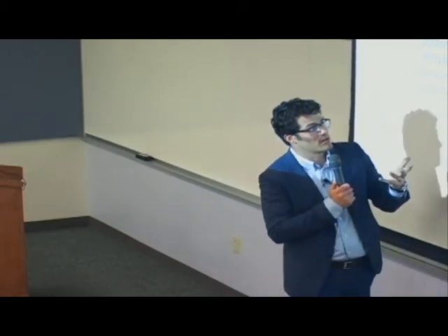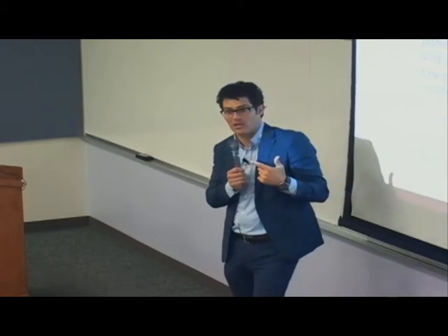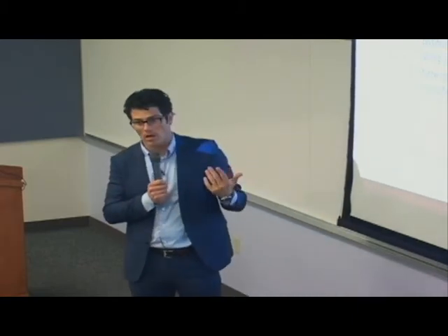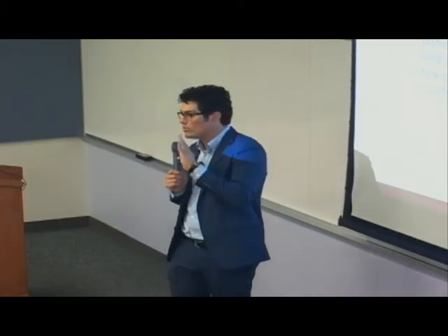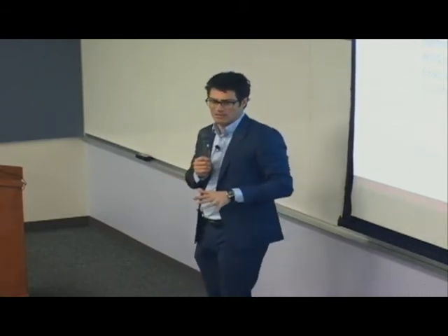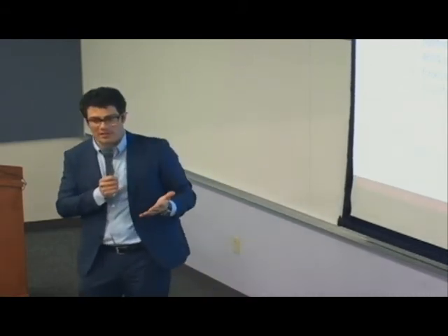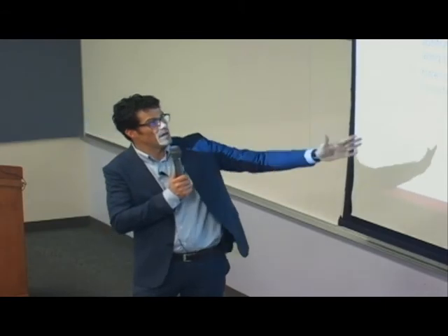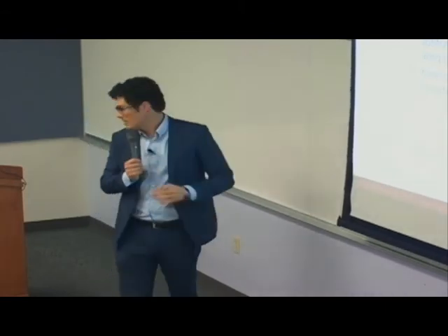And then the other little trick is that you use that force sensor to estimate the normal on the contact. That way you do not estimate the Jacobian in that direction, because the Jacobian is no longer linear there. So we only estimate the Jacobian essentially parallel to that plane.